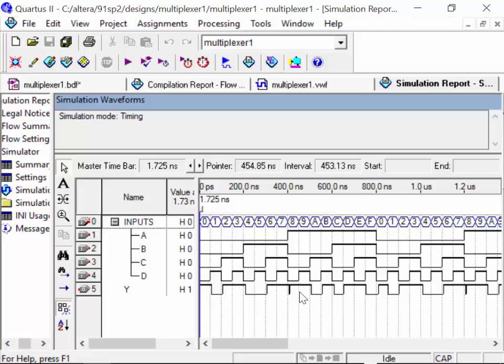D5 is also showing, that's 8, 1, 0, 0, 1, 0, 0, 1, right there. All right, there's a problem here with input number 4. Number 4 is connected to, it shows it's being connected to VCC. 4 should be connected to VCC. That's right, okay. D3 looks like there's a problem.